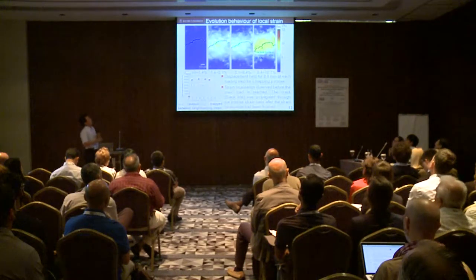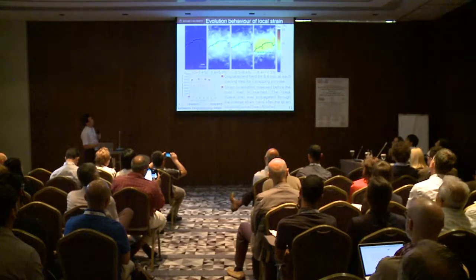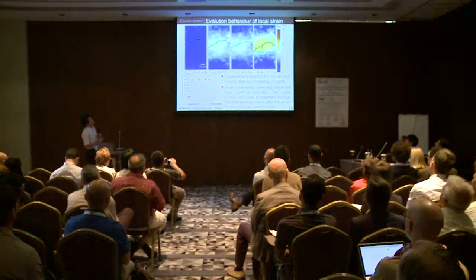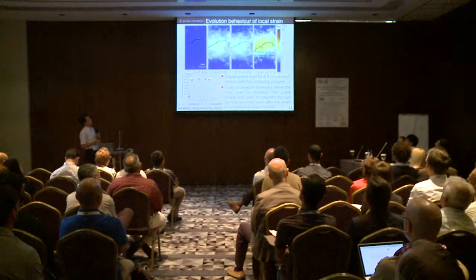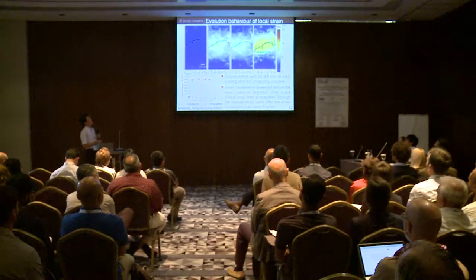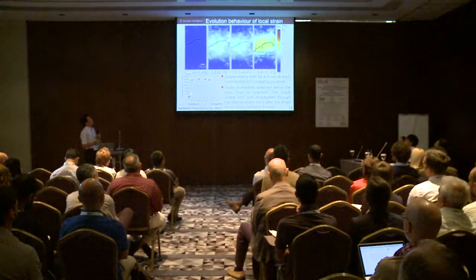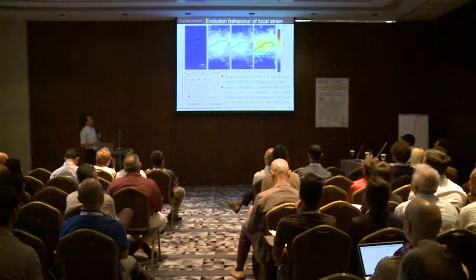So we are now looking at the 3-dimensional strain distribution with loading. This is the applied strain level. And it is shown on the virtual cross-section. And these black lines are the section of a fracture surface, which was formed after this strain level. So we strained the specimen and then fractured it at the end.